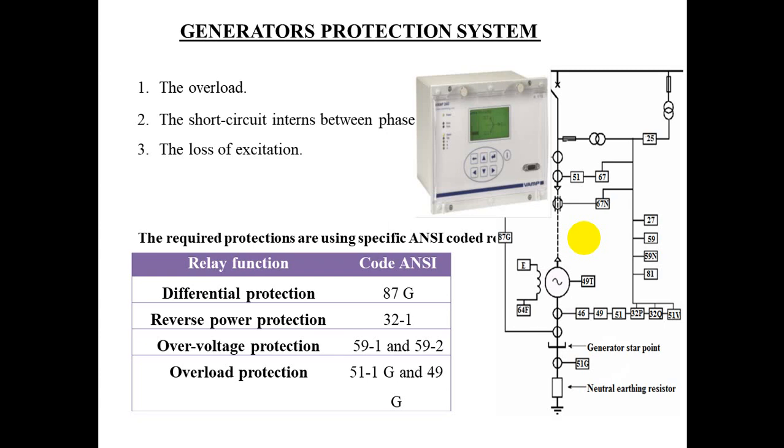If the imbalance occurs due to any external faults or unbalanced loading in the system, it may remain undetected or may persist for a significant period of time, depending on the protection coordination of the system. These faults can be cleared by installing a negative phase sequence relay with characteristics to match the withstand curve of the machine.